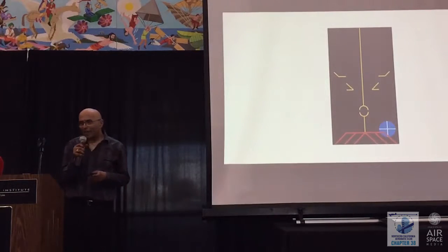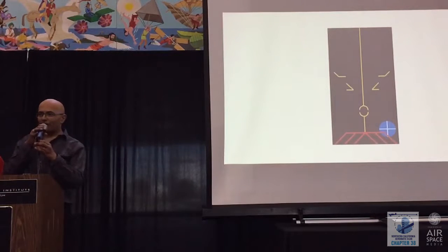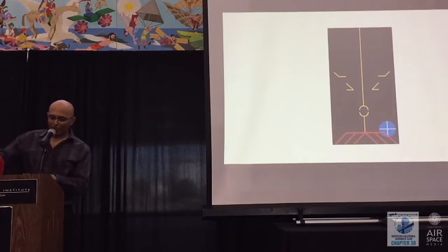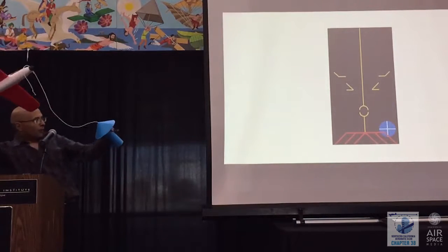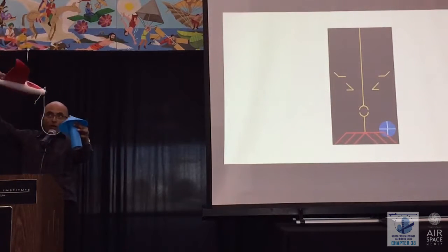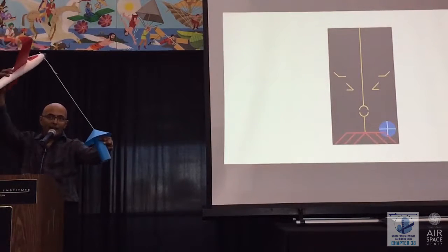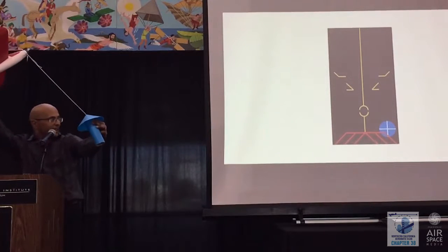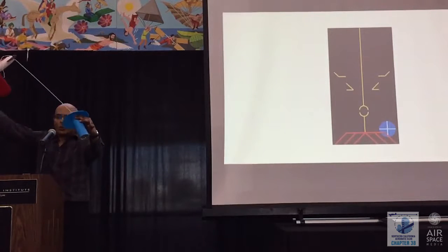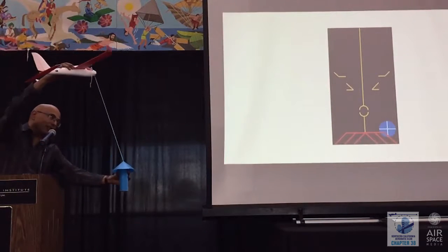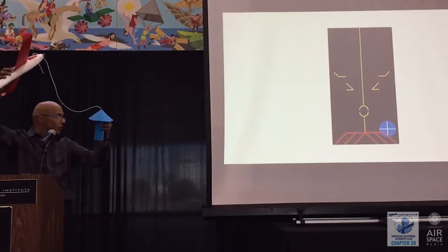This is an example of the fabled base to final stall, and I've talked about that before when I showed you the problems at the airport. So here, the airflow is coming from the right because you're using rudder to turn left, and it's coming from below because you're at a high angle of attack, and it is also small because you're going slowly. And this is where people making a left turn base to final break their airplanes. That is what will lead to a spin.